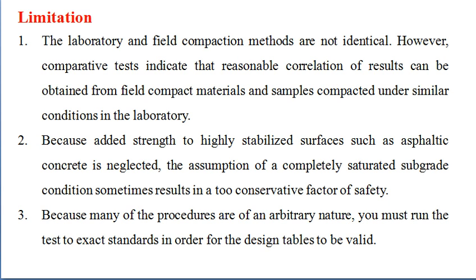Next, because added strength to a highly stabilized surface such as asphaltic concrete is neglected, the assumption of a completely saturated subgrade condition sometimes results in a too conservative factor of safety. And lastly, because many of the procedures are of an arbitrary nature, you must run the test to exact standards in order for the design tables to be valid.